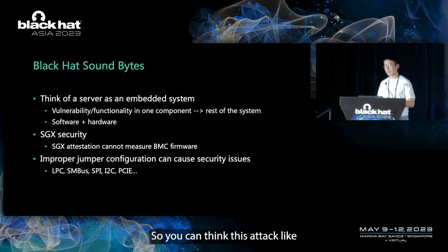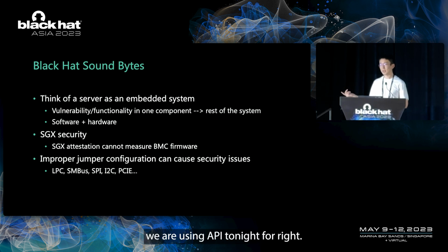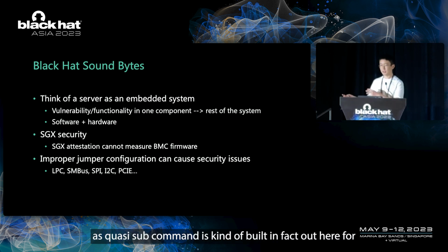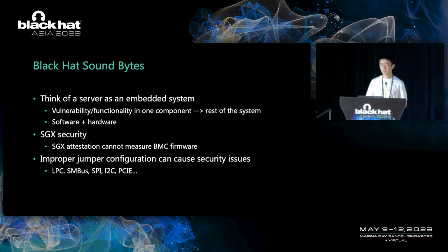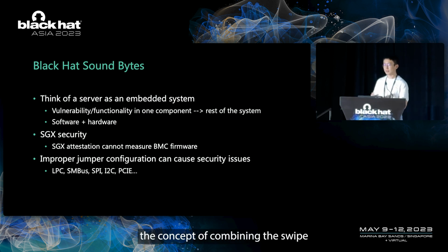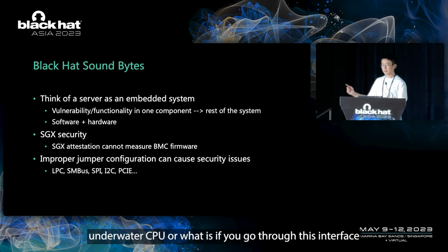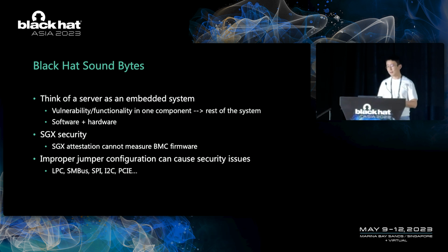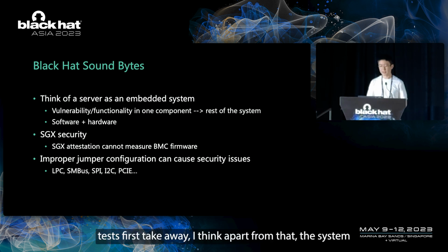In this attack, we're using the IPMI tool. The IPMI tool's I2C subcommand is a built-in functionality with its intended purpose. It doesn't have a vulnerability by itself. But if you think about it in the context of the SGX threat model, the platform security, you can actually undervolt or overvolt the CPU through this interface. That's the first takeaway.